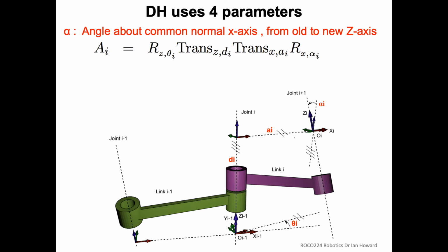axis to the next axis, the transformation we need, in terms of 2 screw displacements. So there's going to be a rotation followed by a shift, then a rotation followed by a shift. In fact, the actual order of those is not important, because the way that the Denavit-Hartenberg is set up, you can actually rotate or translate and rotate. It's actually the same thing in this particular instance.